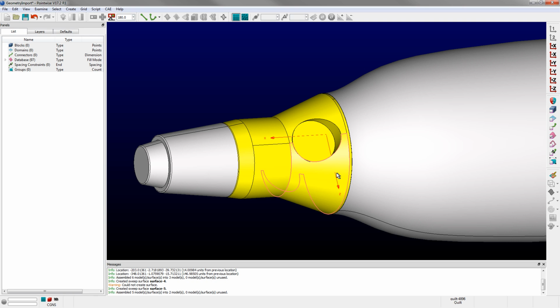It's not necessarily exposed to you, so we expose quilts and models to you to operate on, so you don't have to worry about the underlying database entities. Okay, the problem is if I select this quilt, you'll notice when I hover over this it selects a lot of stuff, and my cursor is this little multi-cursor. That's because I'm hovering over multiple database entities, and to cycle between them I can just hit the space bar. Okay, so I've basically isolated that entity right there.